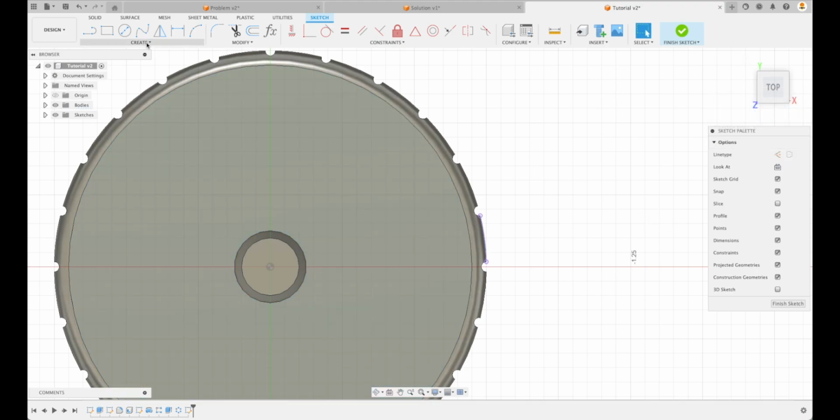Now what do we have? We've got ourselves a midpoint. And if we hover our mouse over there, we should see the midpoint constraint. Boom, that's right at the midpoint now. Now what we can do is create a line, and let's just create it off into space over here. And we are going to use our coincident constraint and constrain those two together. Let's turn this into a construction line by pressing X.